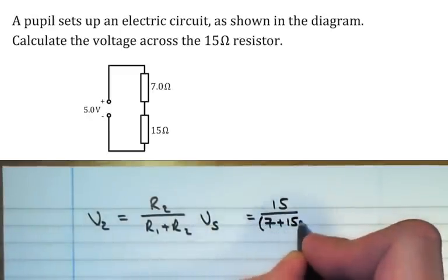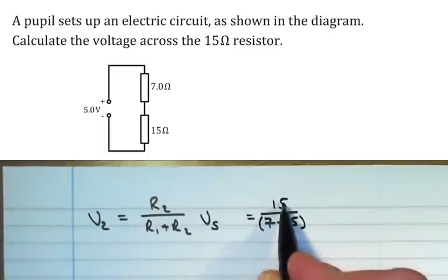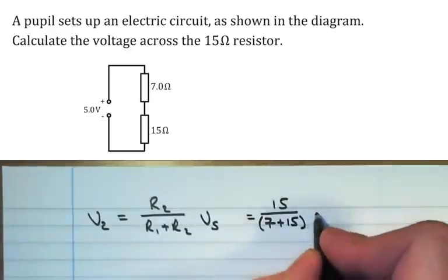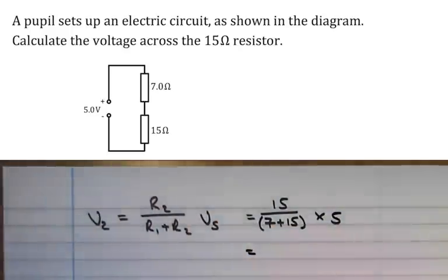Now, be careful with your calculator. And just so there's no mistake, put this in brackets, because the bottom line should really be the total resistance in the circuit. Put that in brackets. Okay, so 15 over 7 plus 15, or of course you could just put in 22, times the supply voltage of 5 is equal to...